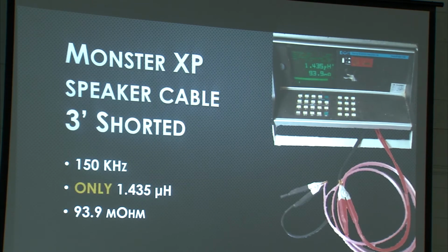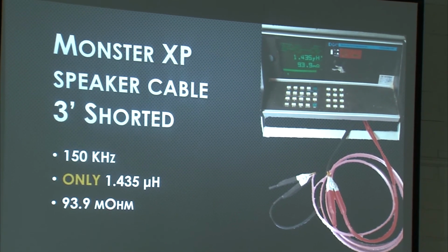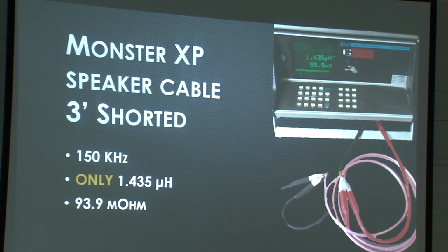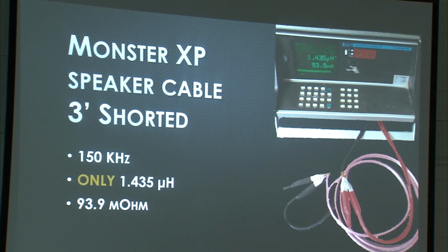Well, here's the really telling thing. This is the inductance of 3 feet of wire to hook it up. You're already there at 1.4 microhenries. So if the resistor is less than that, it's not an issue. So don't chase down the very expensive non-inductive ones. At one point, I chased down some very fancy film non-inductive resistors, and they were all rated at 100 watts, and they all promptly fried. It was very frustrating. And 3 feet of wire is 100 milliohms.